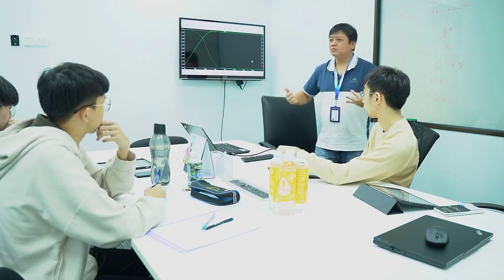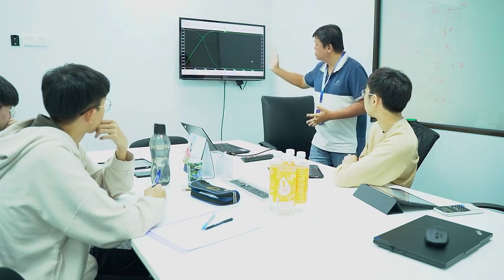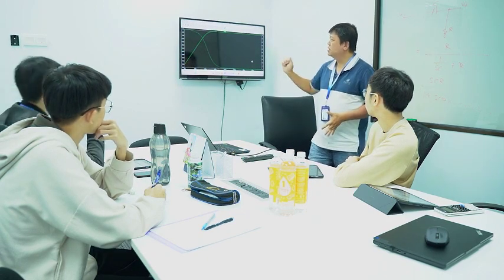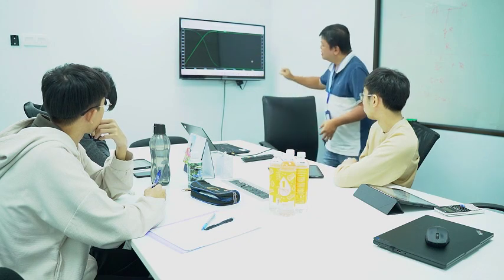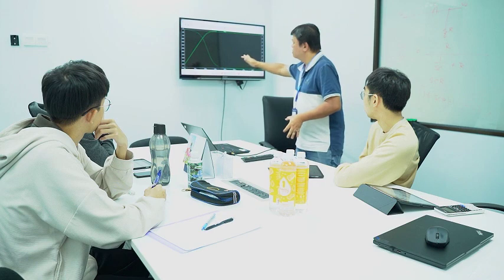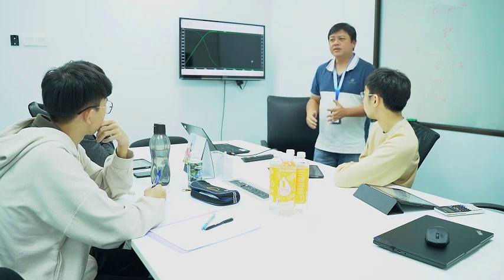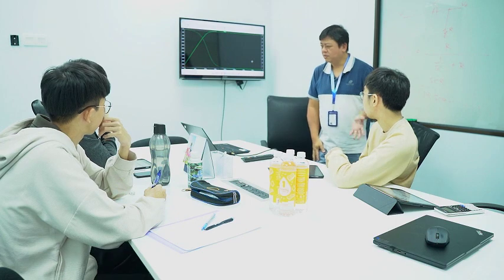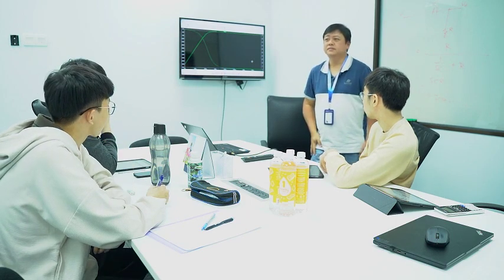Because we all learn theory, we need to interpret. That's why I say interpret. For example, you can interpret: this circuit has one pole and one zero, there's a phase shift, and this is a high frequency filter. So all these things you learn, such as the maximum being a 90-degree phase shift, give very important information. You get it? Understand?